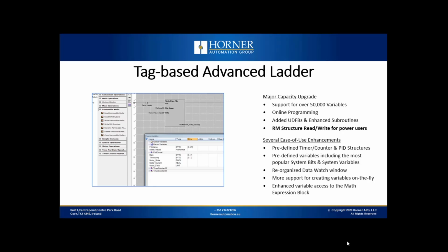In addition to these major upgrades, we have also implemented some ease-of-use enhancements. We've predefined timer counters and PID structures to make it easier to use those features. We've predefined variables such as system bits and system variables. We've reorganized the data watch window to make it more tag-oriented. We've included more variable boxes so you can create them easily as you go. And lastly, we've enhanced variable access to a variety of different function blocks, for example, the math expression blocks.